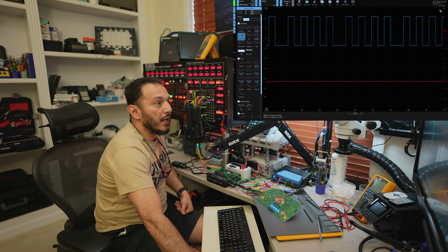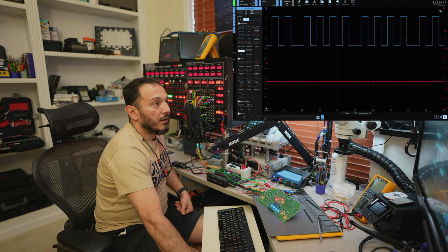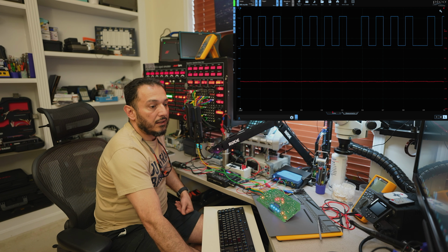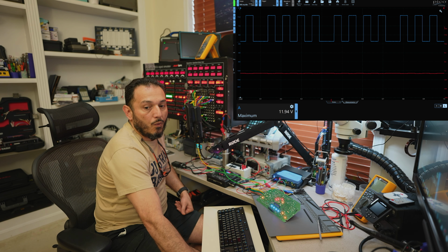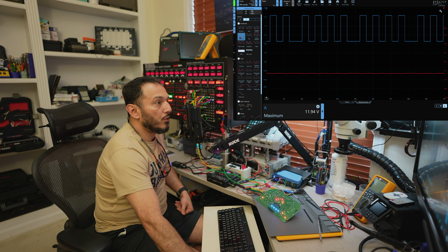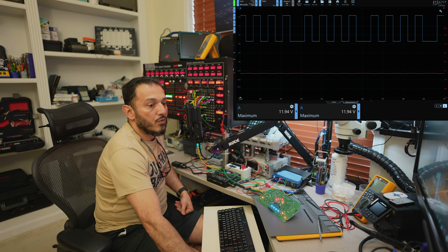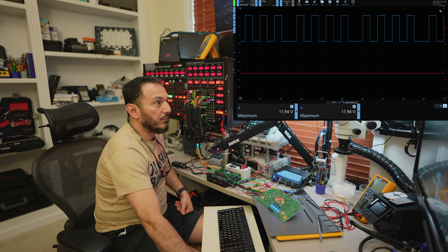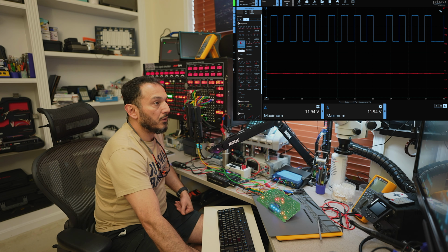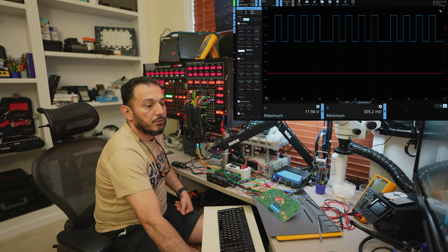So I'm going to add a maximum, and I select the channel. So in 8, now that is in there. I'm going to make this window a little bigger so you can see that. We're going to add another measurement, and we're going to go to minimum into 8, right? So now we got 2 measurements. We're going to do the same thing onto the red channel. I actually put 2 maximums, not sure why. Let me go into minimum.